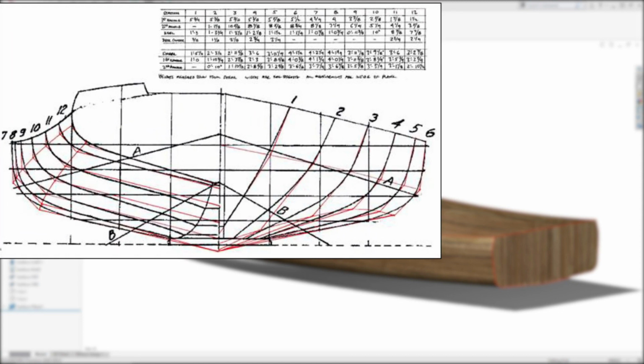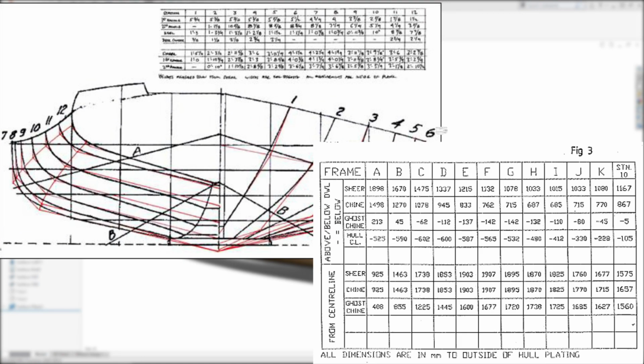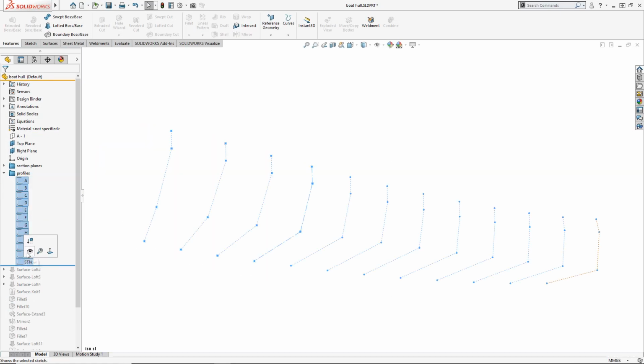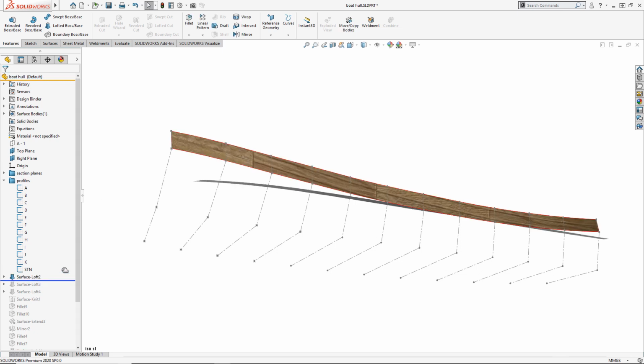the shipbuilding industry, where a shape is defined by taking slices through the geometry. SolidWorks can create geometry in the same way, with the engineer creating multiple sketches and morphing a shape between them. This shape can then be further enhanced with the use of guide curves and/or tangency conditions.